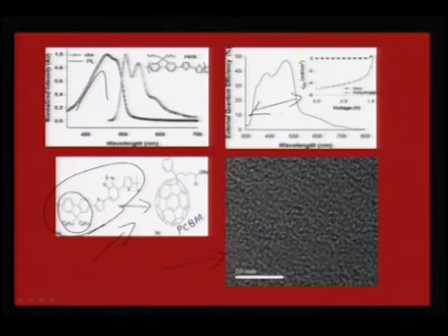for photovoltaic application. And this is the view graph in the inset, which gives you an approximate clue to how this sort of heterojunction can behave. This is in dark and this is the IV curve in light, and you can see that the open circuit voltage, VOC, and the fill factor are quite decent here